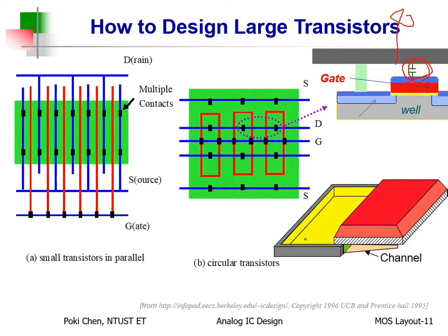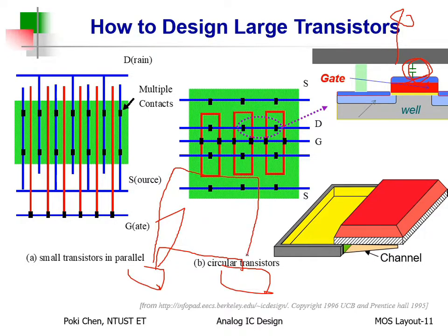But you can see if I am here and the next device is there, from the beginning we can be connected by metal one. Right? You try to reduce the gate parasitic, so you do such a very silly connection. Oh, to the top, then go back to connect your neighbor. It doesn't make any sense.